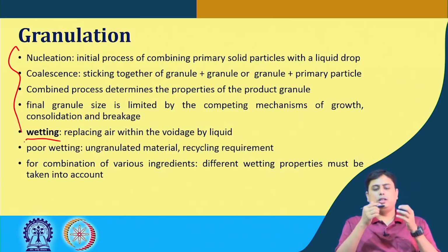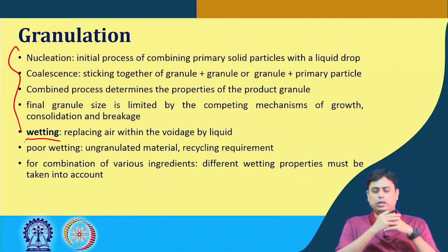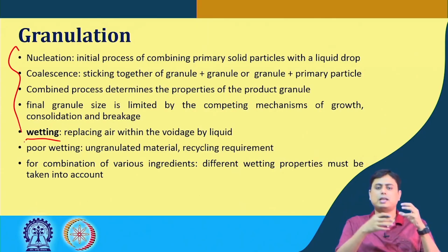Poor wetting means the chances are there will be ungranulated material, because the liquid bridges are not formed due to the absence of liquid in those pores, or the surface wetting of the particles. If the liquid binder is not present on the surface, it is not binding the particles together. So these ungranulated particles have to be recycled again for efficient operation.